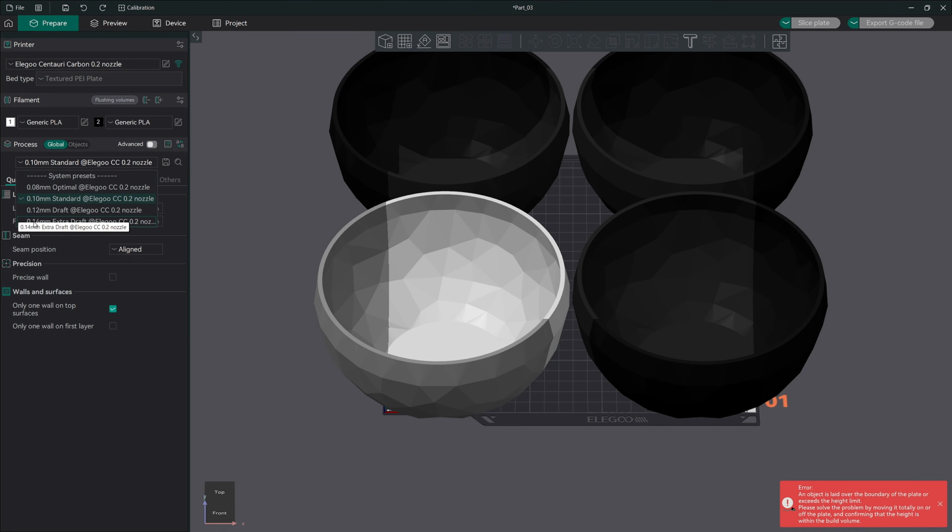You'll see that the range of layer heights shifts from a 0.14mm down to a 0.08mm. That's because smaller nozzles can produce finer details, but at the cost of slower print speeds. So it's important to keep in mind that each nozzle size has its own layer height limitations. The general rule is simple: the smaller the layer height, the higher the detail, but the longer the print time.